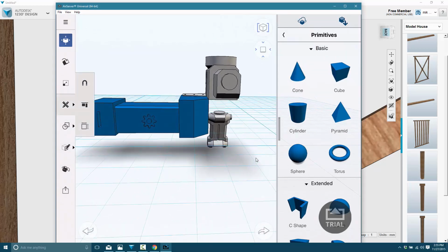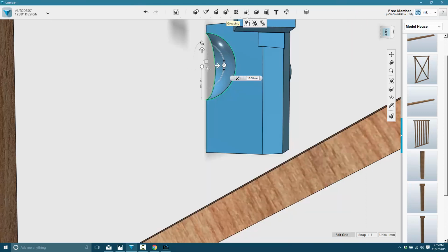There's your snapping tools, your differences and alignment stuff, subtract and union. So you'll notice there's subtract and union, but if you go back to the desktop, I always pick the wrong one. Let's see, where did it go? Here we go. There's merge, subtract, and intersect. So there's no intersect for some reason on the mobile. You're editing. One thing that's sadly missing is split face, and there's no tweak version available on here. But otherwise, you're talking kind of the same app.